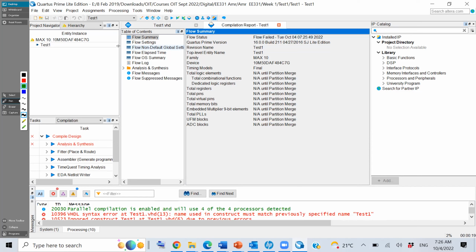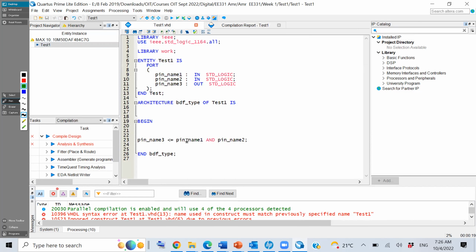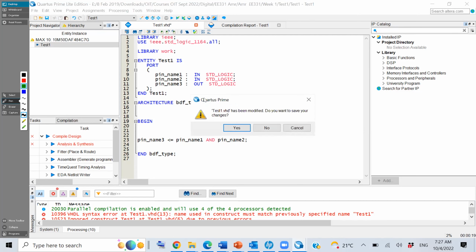Let's go and see. As you can see here, we specified test1. Now it is not matching. This entity started here, but it hasn't ended. It must be ended. So it couldn't end test1. It has end for test, which doesn't exist. So this is another error. We are ending something that doesn't exist, and we open test1 without closing it. So this has not been processed. So when you come and say this use test1 hasn't been processed, it will give you a third error, maybe fourth error. So I put here test1 and compile again and save again.